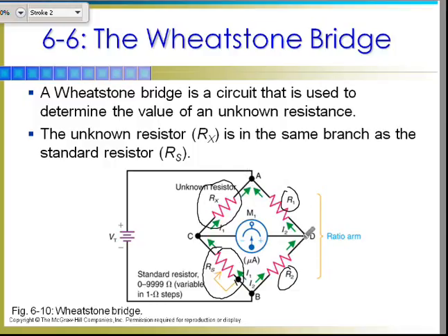Now in between, in the middle of the two branches, you install a galvanometer, which is a very sensitive current meter. And what it would do is the ratio R1 to R2 is going to produce a known current. And then your other side will also have a known current. Now, if these are out of balance, you will then have another current path to flow here, and the galvanometer is going to register so much current because one side will have more potential than the other.